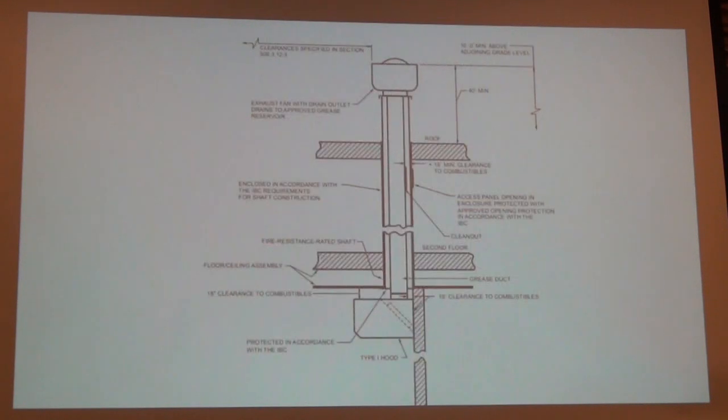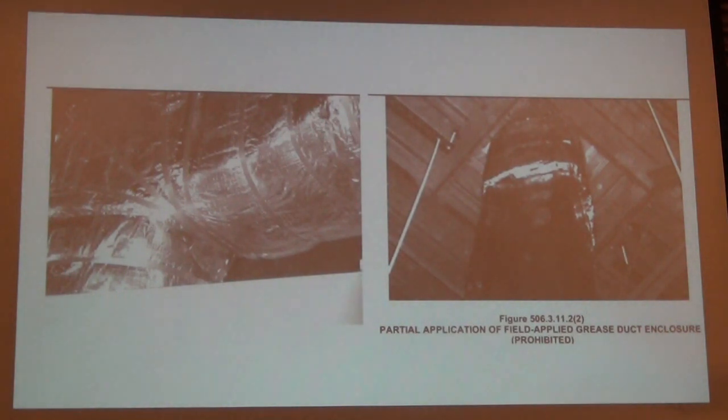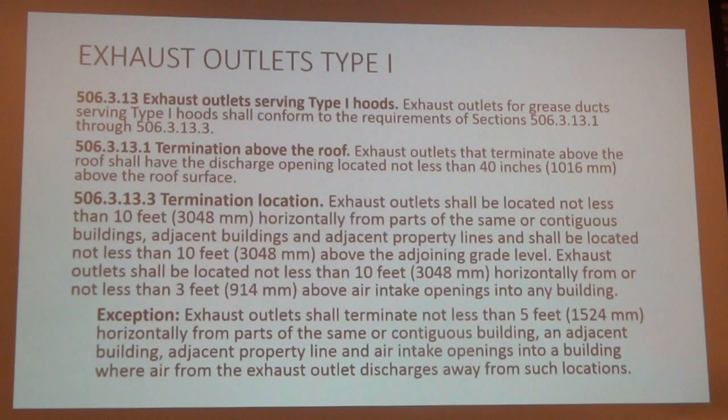On that, I think I got a picture. So here they're showing the grease duct enclosure. And they're showing here one where it's just partially enclosed, and that is prohibited by code. By manufacturer as well, too.